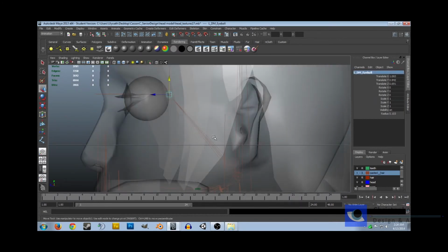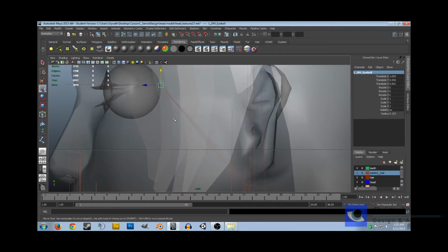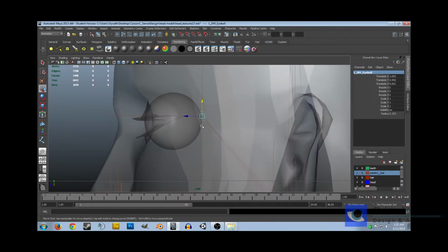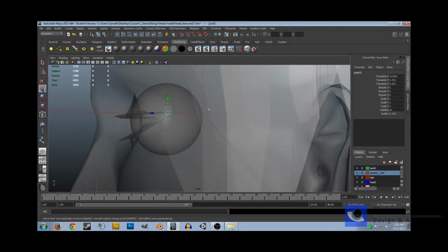Now we will start creating the joints needed for around the eyes. Start by creating a joint with the head joint as the parent, and have it positioned right behind the left eyeball. Don't worry about creating one for the right eye for now. You will see why later. Next you will be creating 2 joints, both of them at the center of the eye and slightly above and below the Y position of the joint's parent, as seen here.